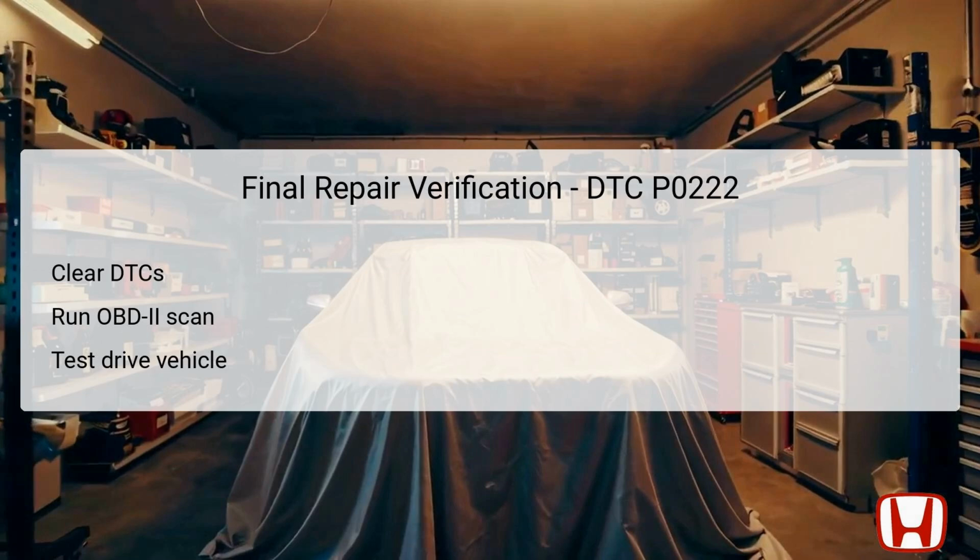Once all troubleshooting steps have been performed and any necessary repairs are made, it's essential to verify the success of the repairs. Start by clearing any DTCs present in the PCM using a scan tool. Following this, conduct an OBD2 scan to ensure that the DTC P0222 does not reappear and that other systems are functioning correctly. A test drive of the vehicle is crucial to see if the symptoms related to DTC P0222 have been resolved and to provide insight into the vehicle's normal operations under various driving conditions.